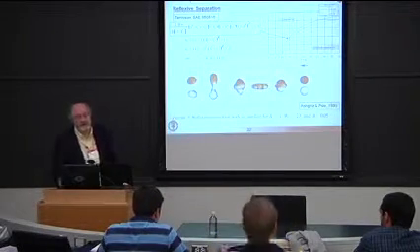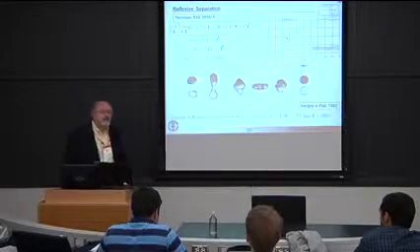Has it been reestablished like a new packet, like because you said originally? Exactly, yeah. And that's great because essentially you're reducing the number of parcels when two of them collide. Or you can just simply change the number of drops in one parcel versus in the other, depending on the outcomes that you have here. The other problem is when you have breakup, because now a parcel can produce many more droplets. And if you make a new parcel and you add that to your already thousands of parcels, pretty soon you can have problems with computer storage. So you have to be a little careful about how you assign new parcels in a simulation. But we've worked through that as well in some of these spray models.